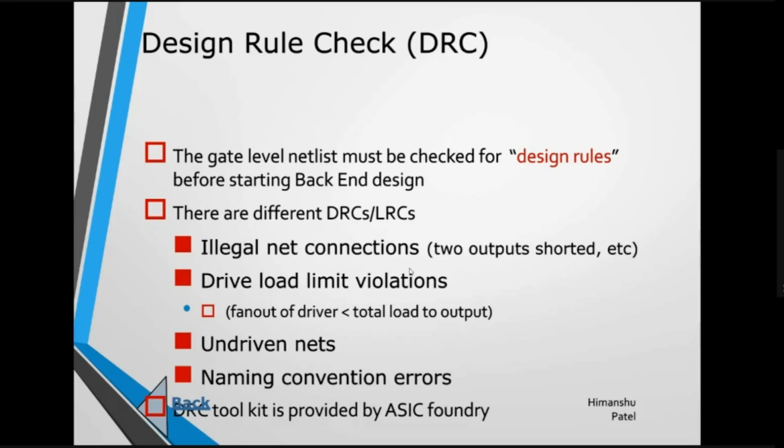The only reason is DRC. They have to clean the DRC to proceed further. If you have DRC, then you cannot tape in. So DRC means design rule check.